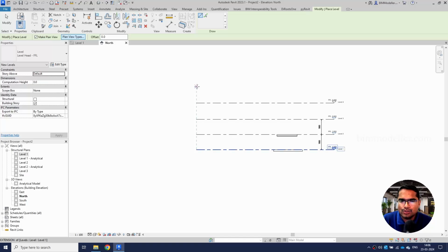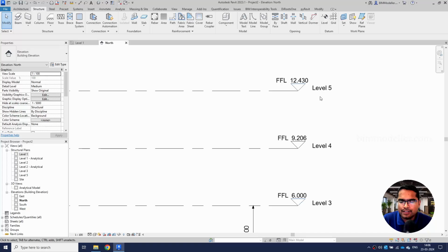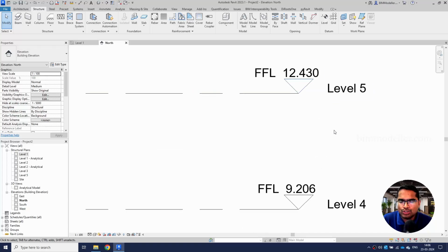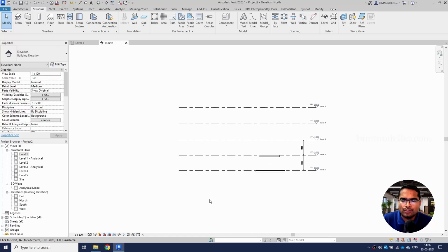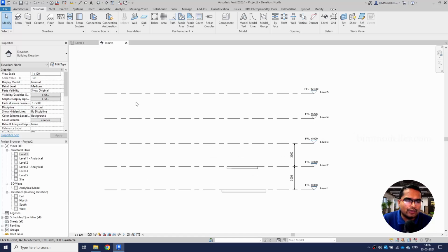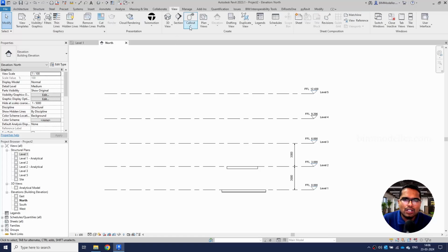I'm going to go ahead and create another level. Now you see that it is in blue shadow. So level 4, level 5, automatically the numerical value will be incremented. Wherever you draw it, it could be on the bottom, the name will be incremented by default. So what to do for level 4? We need to create a view.